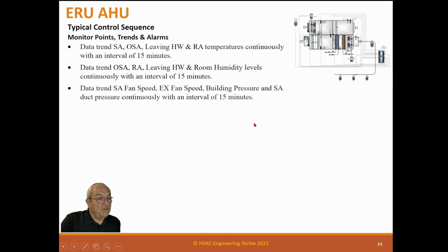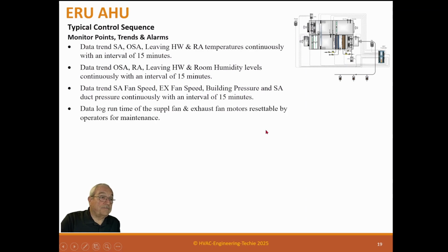Now, if one of these alarms trips and you're an operator, then you'll go check everything out. If you can't quite figure out what's going on, then you'll need to set up another trend at maybe every 15 seconds or every 30 seconds. Say maybe every 30 seconds to do true diagnostics. 15 minutes is way too long to do true diagnostics, but it's there for just an operator check to see what's happening. Data log runtime of supply fan and exhaust fan motors, resettable by operators for maintenance.